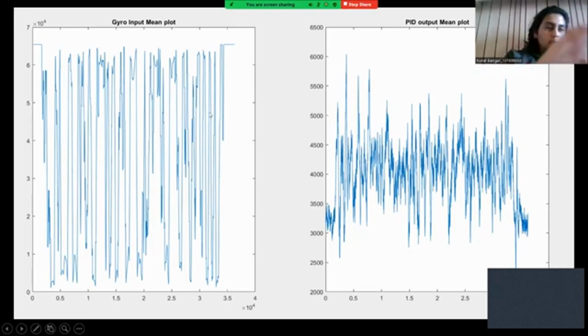as we had hoped, so as to get a clear picture of whether or not the PID will be working properly. And as we can see, the variations and the errors are minimized, and the spikes and the errors have been lowered as we increase the gain. We can see that the value is much more settled around one particular region as compared to the input.